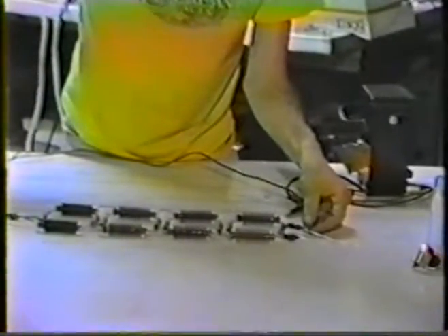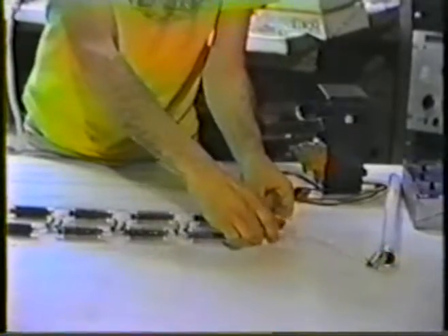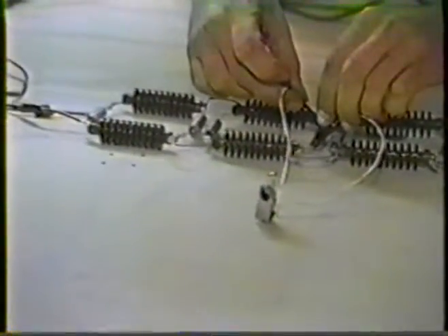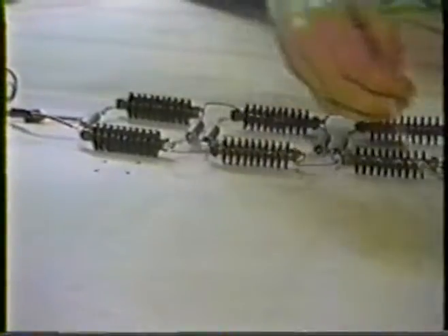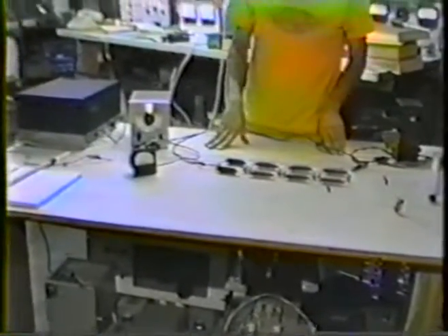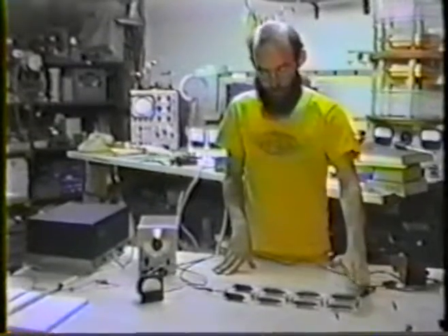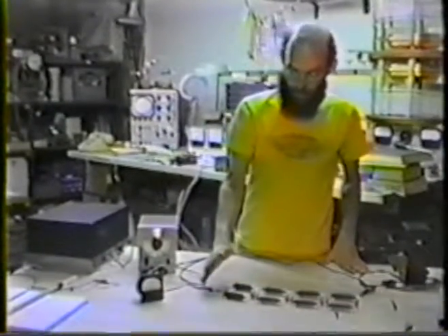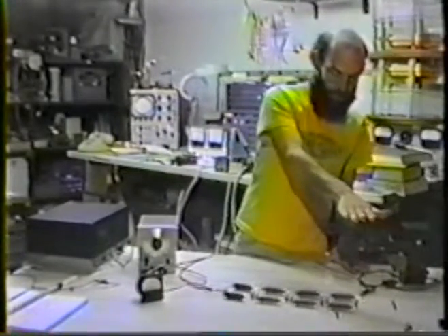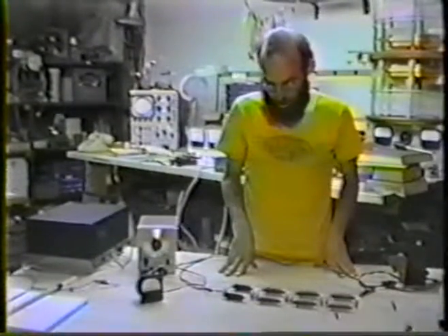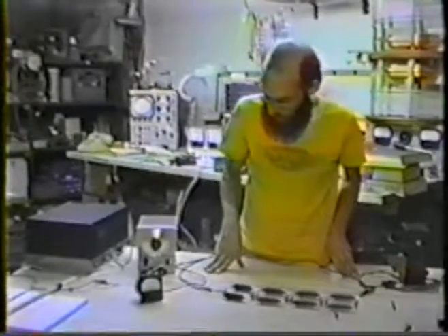Now with the dielectricity, we can start from the end, bring the bulb off of overload a little bit. And we can probe down to the next stage. It's a little weaker. And here it's not even measurable anymore. So the dielectricity has dropped off going this way, and the magnetism has gone this way. So we can see our classical distribution of magnetism and dielectricity on a TEM line, where the magnetism rises towards the low impedance source, and the dielectricity rises towards the open circuit or high impedance load end of the line. Of course, no load being hooked up at this point.